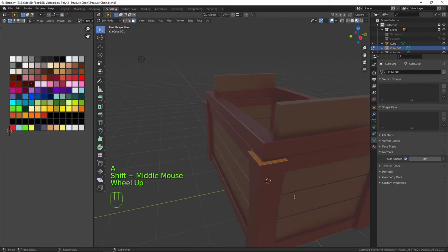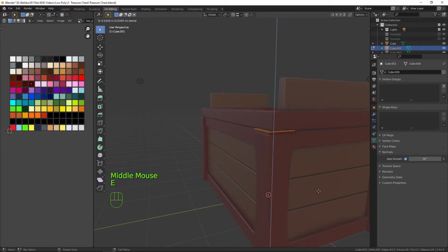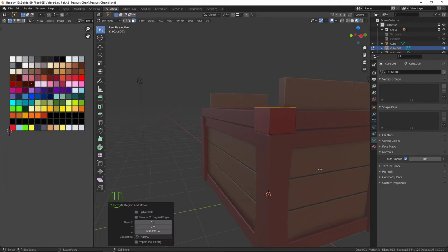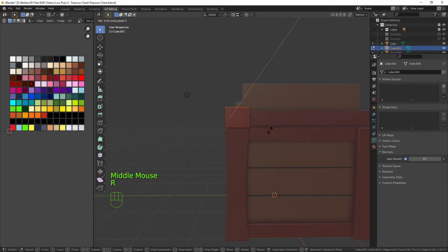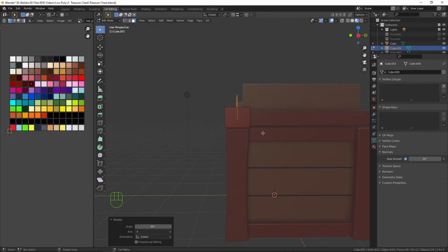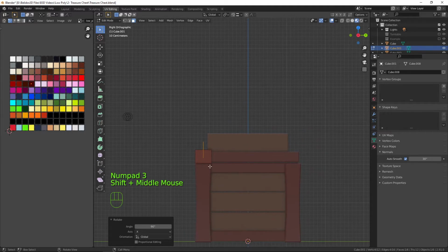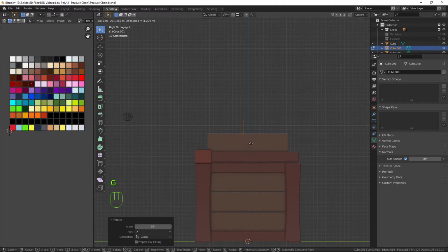And now what I can do is I can select it and I can press E and extrude, and I'm going to extrude it up to about there. Right, I'm now going to press Y, and what that does is it separates it from the actual mesh. And I'm going to press R X 90 to bring it round to there, and I'm going to move it to just before, so that it's just above this piece here, and just before the blue line.